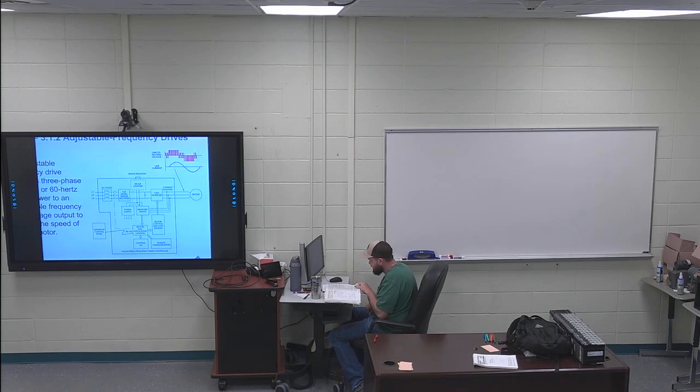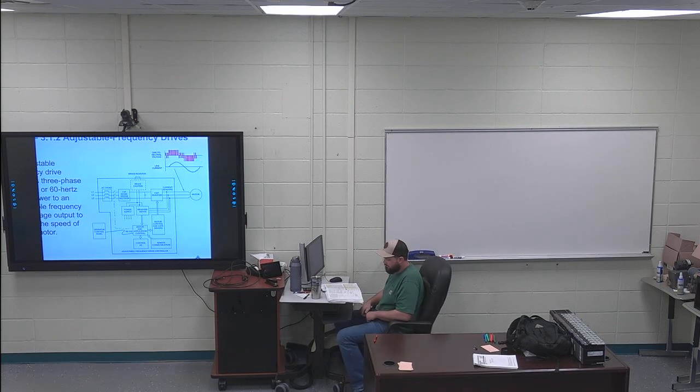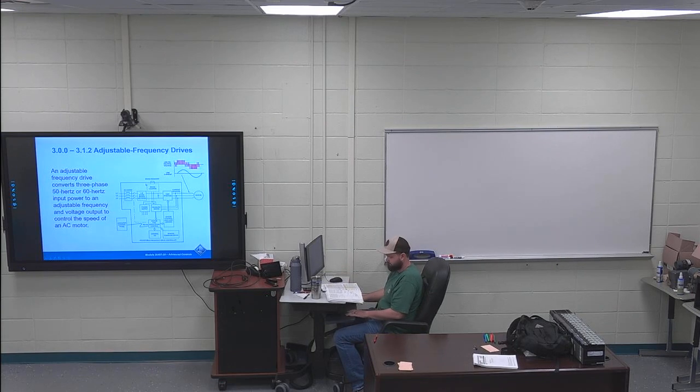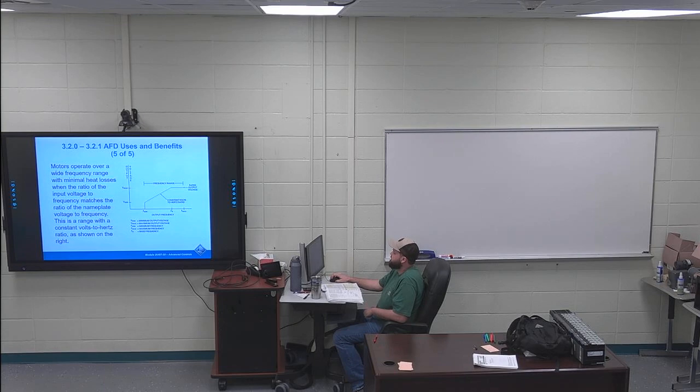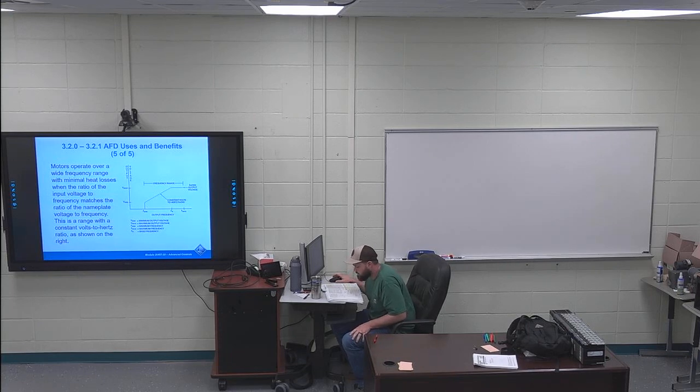Moving on to page 28, you need to look at the operating frequency range, which is figure 24. This picture right here. You're going to have several questions come off of this picture. I've got the first 2 or 3 sentences highlighted. Motors operate over a wide frequency range with minimal heat losses when the ratio of input voltage to frequency matches the ratio of the nameplate voltage to frequency.